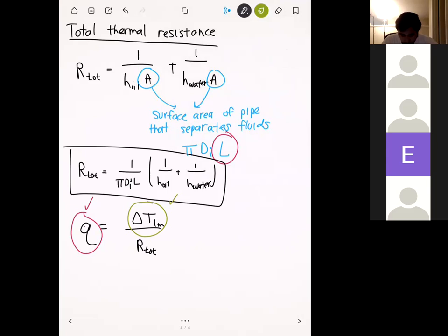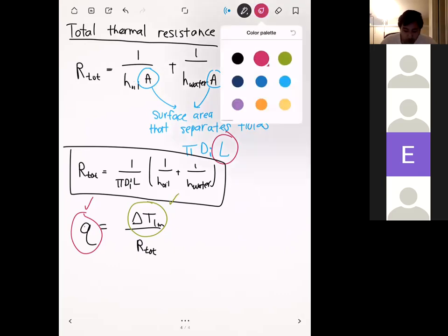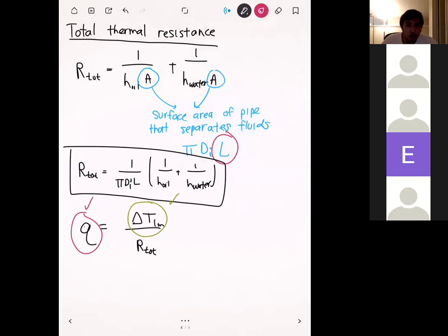First we solve for Q, then solve for delta T_lm, plug all this in, and use that to solve for L. Let's start with Q. Q is pretty simple, because it's the amount of heat the oil has to lose to drop from 100 degrees to 60, and we're given both of those in this problem.